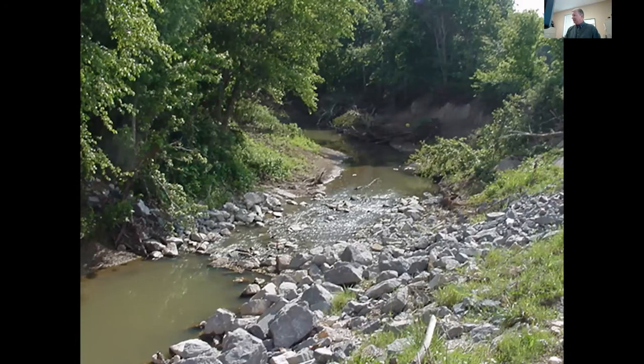Here's one you can see in a very degraded channel that a lot of overfall is being taken out of the channel at these riffle locations. So these are generally spaced anywhere from 75 feet to a few hundred feet apart. That depends on the channel width and the channel geometry. But we space these, not always at even spacing either. Sometimes they are 75 feet for a while and then they'll switch to a longer spacing or more. But it's an effort to recreate this riffle pool and give it a protected place to actually erode.